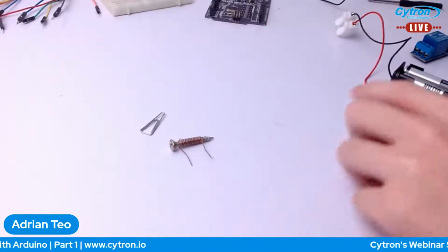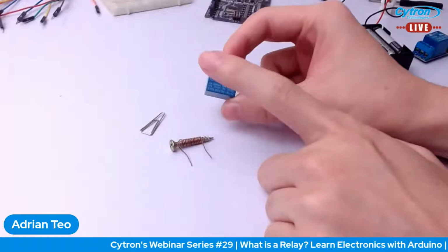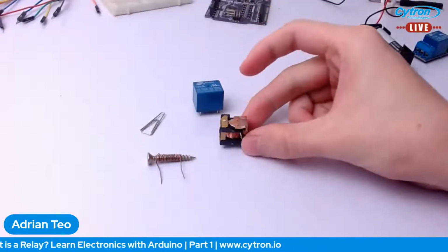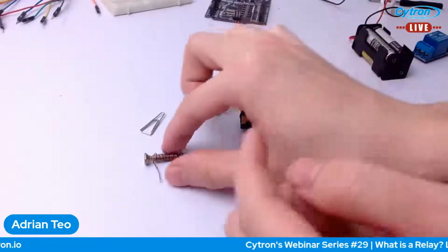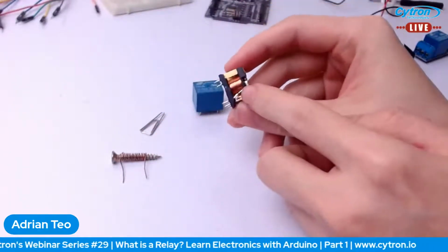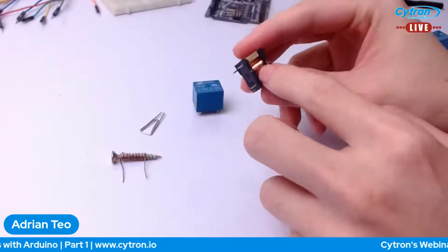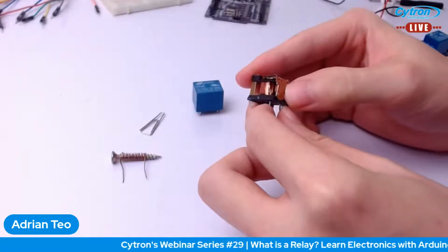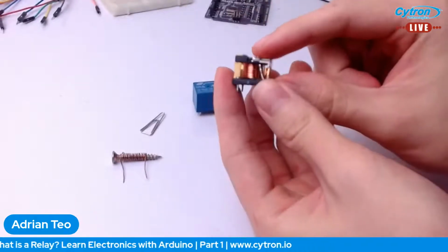So this is an electromagnet, and this is a relay. I'm just gonna go ahead and tell you what's in a relay. A relay is basically a piece of electromagnet like this, but in this form. Okay, this is me opening up the relay to expose the coil. So by turning the coil round and round around the screw, you create an electromagnet. Over here, there's a coil, you see, copper, going round and round in circles on a shaft in the center, and then if you apply a small current like the battery at these 2 pins, then it will actually turn this switch down.